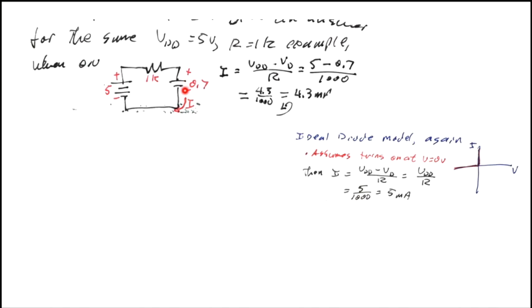If we used a capacitor, then it would work dynamically correctly, but this will handle DC. DC is just fine. So it's a kind of weird amalgam of some concepts, but if you just understand that the model has a 0.7 volt voltage drop for the diode, and you put it in with the high side to the low side facing the same way as the diode current flows, then you could solve this for I is VDD minus VD over R, or 5 minus 0.7 over 1,000 ohms. In this case, that gives us 4.3 milliamps.